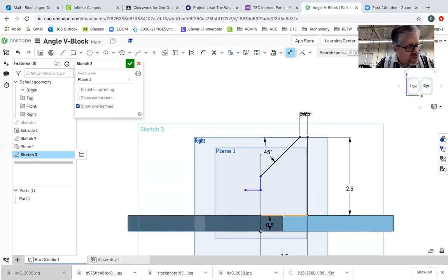I'm wondering about the 3 inches. Okay, so I don't have this in the right place, right? What if I were to, let's escape. I'm going to delete these 2 lines and just redraw them. This is too long. So let's see here. What if I were to do L for line and pick on this point? Yeah, I'm going to escape and delete this line.